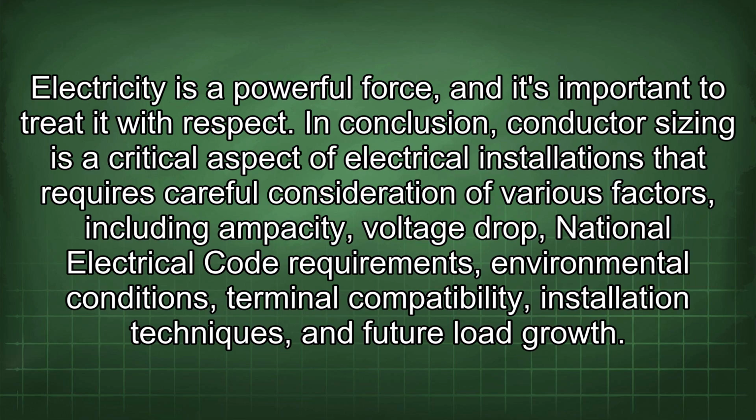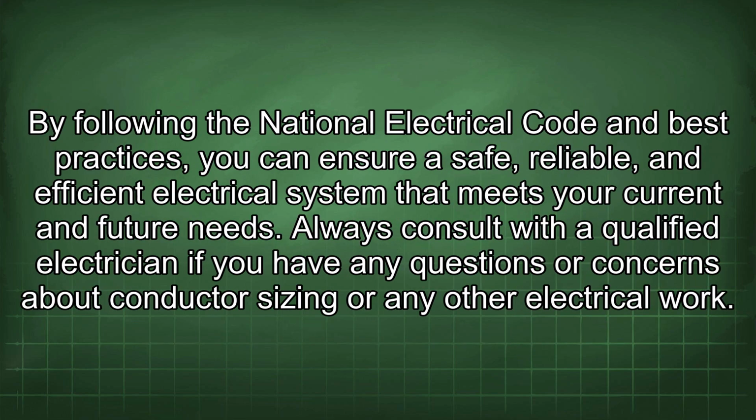In conclusion, conductor sizing is a critical aspect of electrical installations that requires careful consideration of various factors, including ampacity, voltage drop, National Electrical Code requirements, environmental conditions, terminal compatibility, installation techniques, and future load growth. By following the National Electrical Code and best practices, you can ensure a safe, reliable, and efficient electrical system that meets your current and future needs.